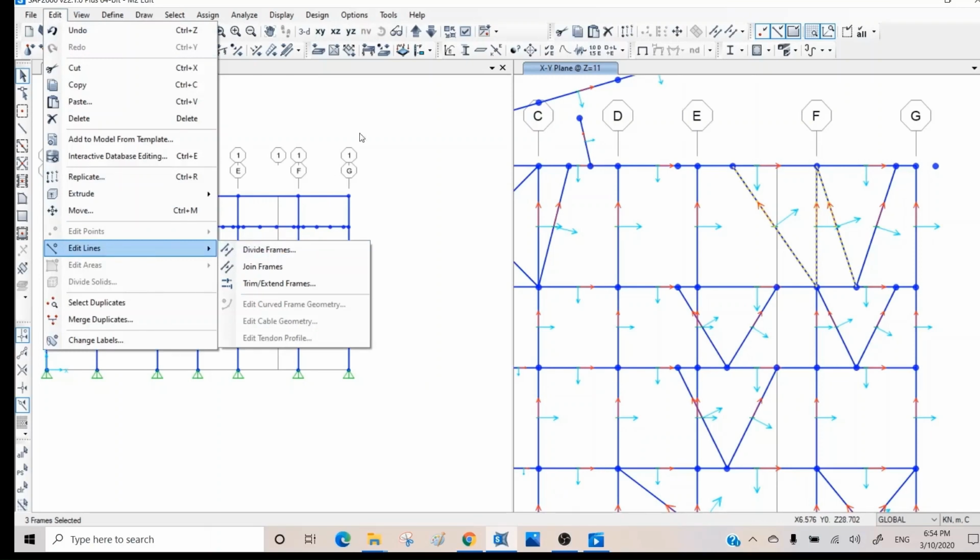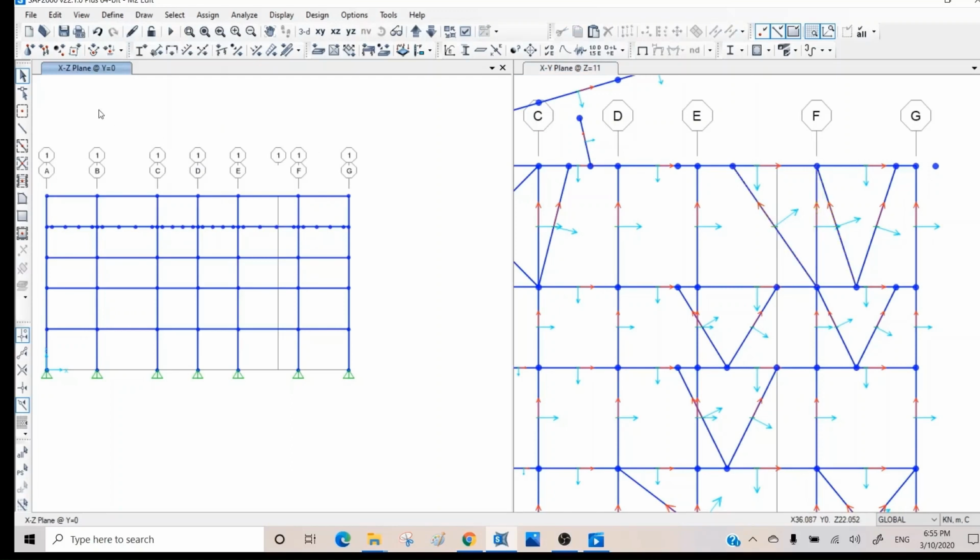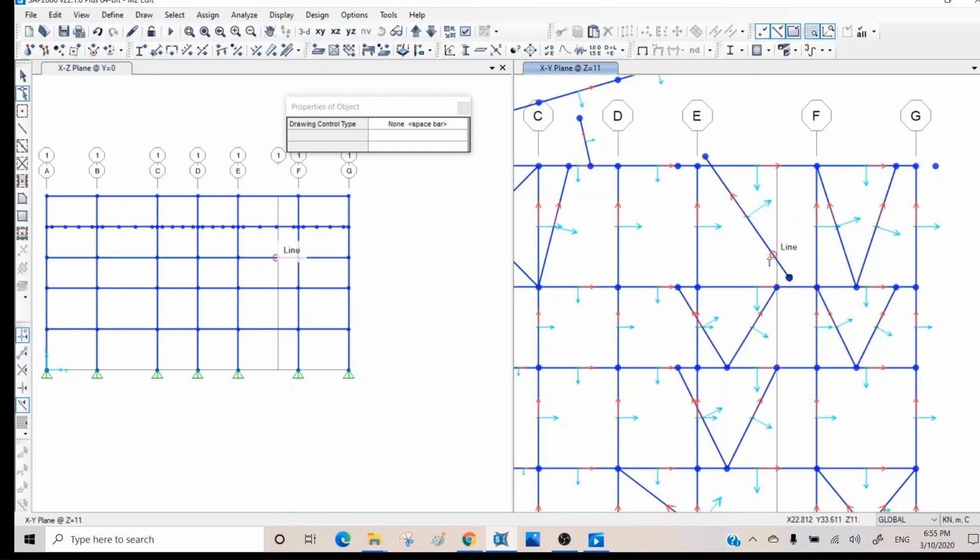The other thing you can do is using this set reshape element mode, which is very useful. Again, I'll talk to CSI about that, but currently what we have available is this, that when you click here, you can see just I and node will be highlighted. That means you can move this frame. If you click here anywhere, you can move this frame like this. And if you click here, then you can move it and put it wherever you want.